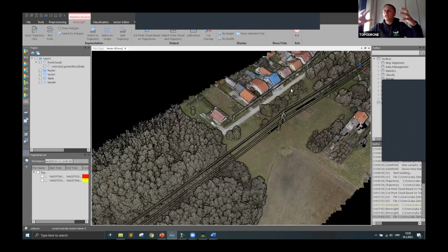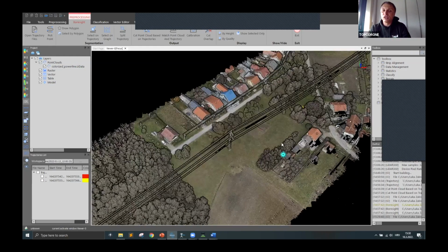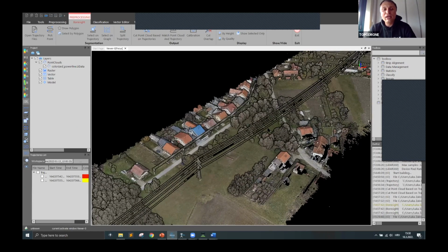In this case, you will get much better information to really colorize power line infrastructure. It's a very good idea not only to point the camera at a 90 degrees view, but to make an oblique flight as well, and you can easily make it with a separate camera installed on the gimbal. Yeah, definitely, because the LiDAR has more field of view than the camera, so it's better to have better coverage with your oblique